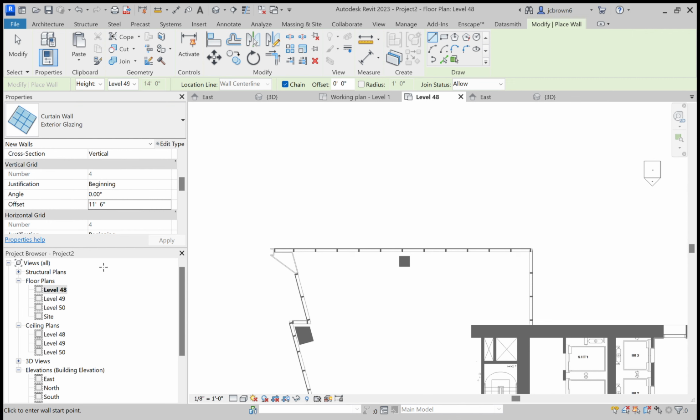So we want to set a mullion on this window to go up to 11'6", because this is probably roughly 18 inches. And that gives us enough room to clear this 13 feet between the top and the bottom. So it's just kind of doing the math of where this mullion ends up. And that's where we get the 11'6". So when you do these for other projects, you'll have to determine that so that you can create your mullion grid. So you'll use 11'6" for this.